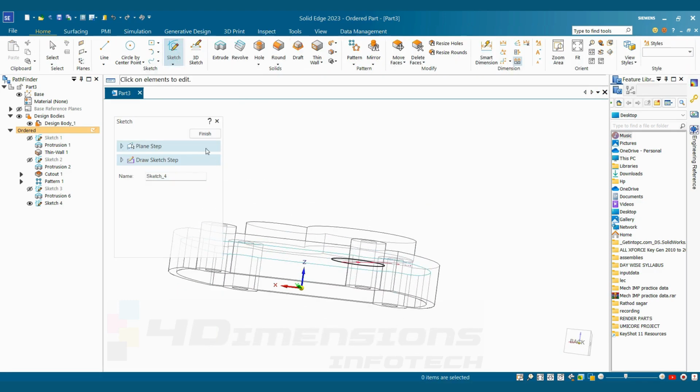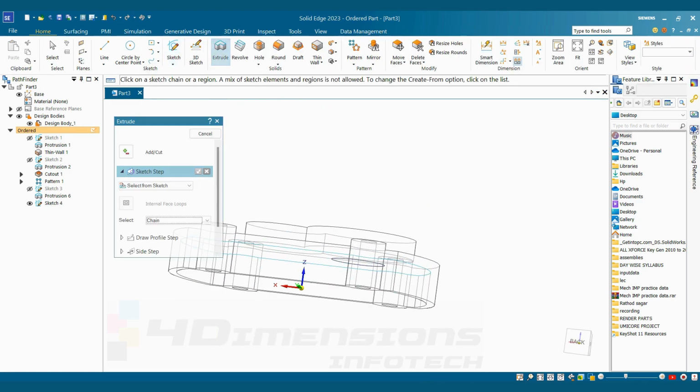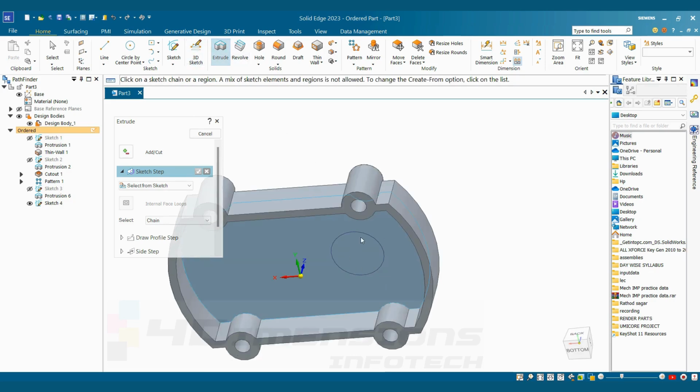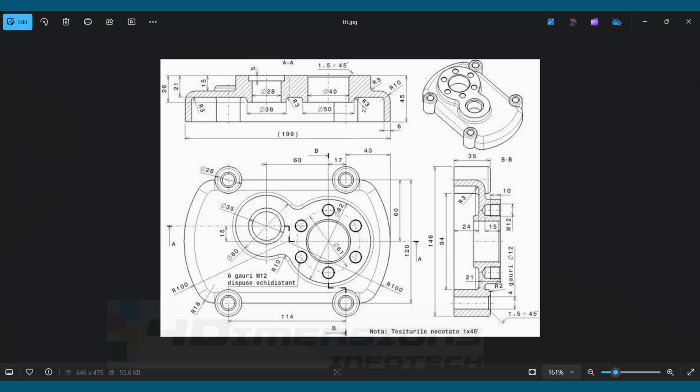So the extrusion here is given as, first we'll change the view style, make it normal, and now say extrude. Select the sketch, say OK. So this extrusion we required here, the distance is not given directly, but you can see from above face the distance is given 26.